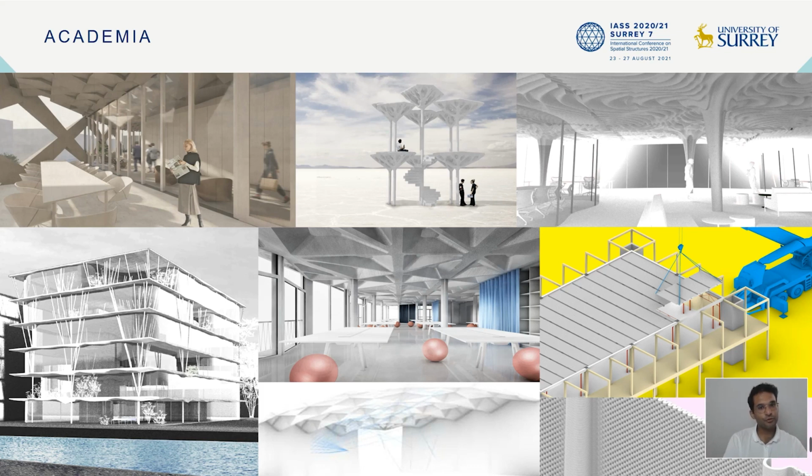Also, one thing that we wanted to focus on is modularity. We wanted to do a prefab construction and then assembly on site. And also, one of the biggest points that we wanted to focus on is formwork. So we do not want to lose any formwork or create it with a material that cannot be reused or which is maybe not sustainable. And we wanted to create a formwork which is actually going to be used on site to be not lost but be permanently inside the structure.